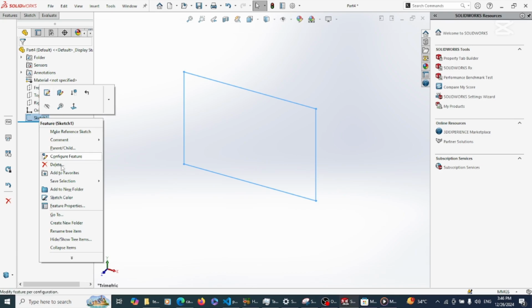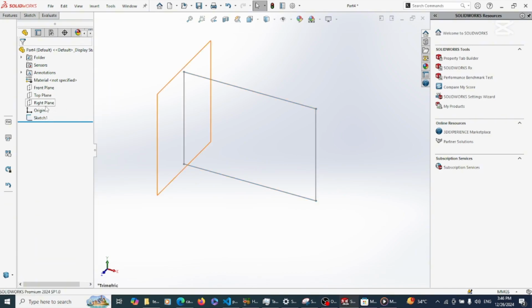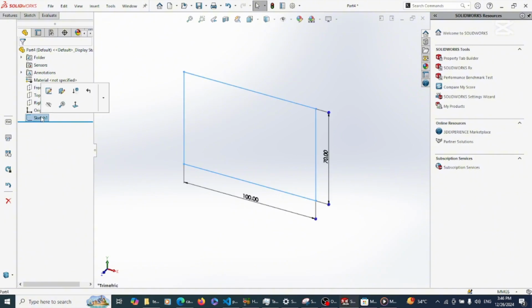If I want to delete the sketch, I will choose the delete command. If I don't want to use the delete command, I will just select the sketch by left clicking once, or using my touchpad and touching once, and use the delete key on the keyboard. The delete key is spelled delete on it, or DEL, not backspace. Backspace is for deleting text, not an item.